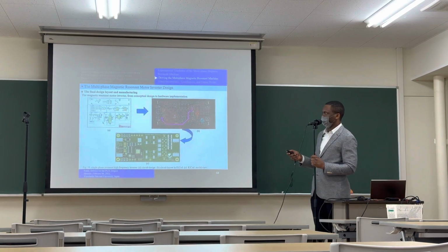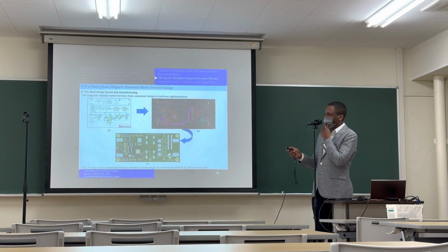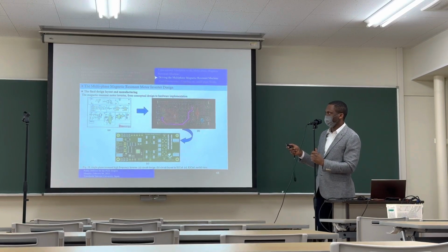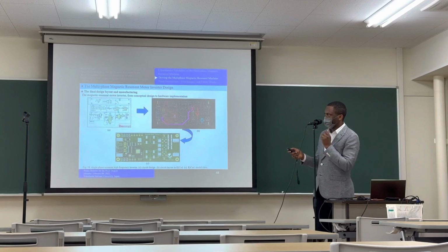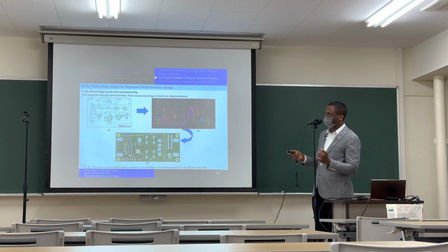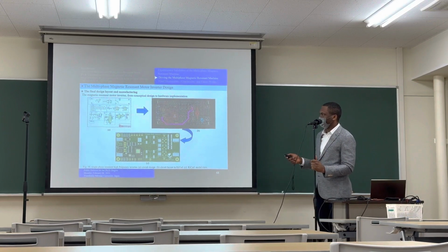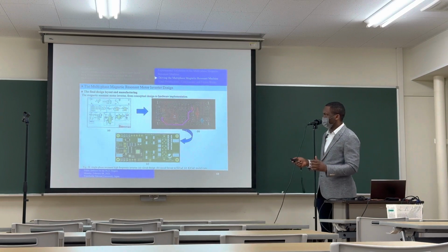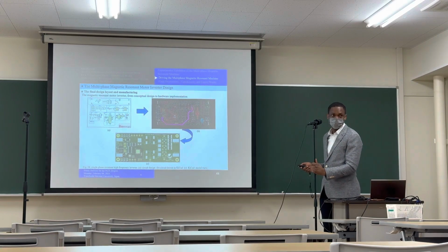Now the next step is to design the main electronic circuit to create what we did by simulation, and this is the main design of the machine. This is the main amplifier part, and this is the main microcontroller. And these are some parts to indicate how current flows inside. We have some gate drivers, and then we have some part where we connect the two boards as master and slave. Then we translated this electronic circuit to a PCB board. We drew the PCB in KiCad, and after drawing that, we made the board itself.